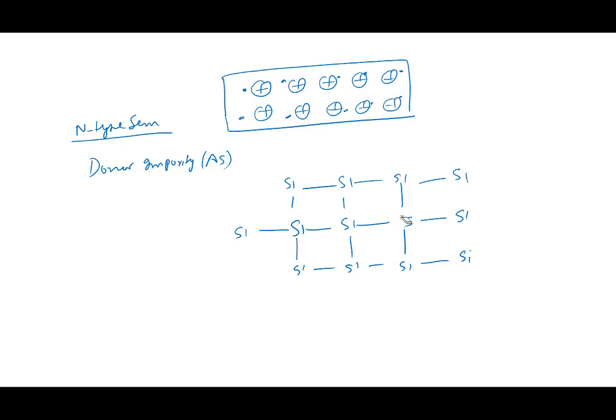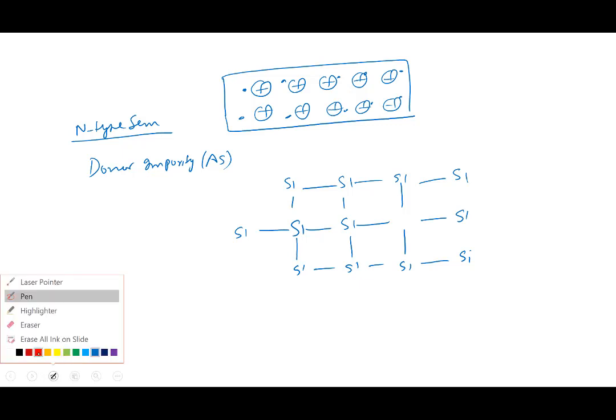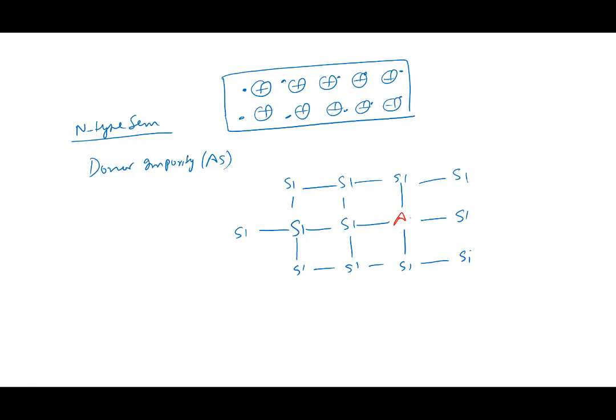That's what the doping process does. It displaces the silicon and replaces it with an arsenic. This arsenic becomes positively charged and donates this particular electron that you see to the lattice. You get one free electron. That's the process that we call doping. You've added an impurity. So this is the picture.